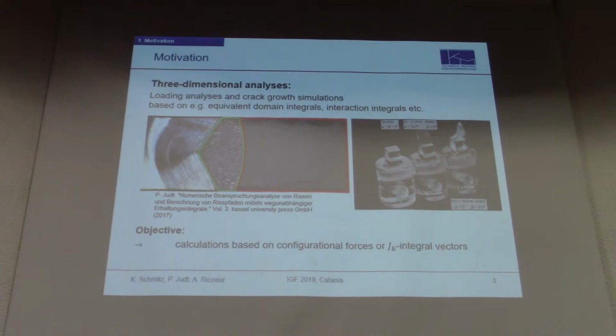three-dimensional crack growth behavior. For example, when we want to observe curvature of the crack front due to mode 1 loading, or crack deflection due to mixed mode 1-2 loading, or also the twisting of the crack front due to mixed mode 1-3 loading. Normally those calculations are based on, for example, equivalent domain integral formulations or interaction integrals. But the objective of this work is now to do these calculations based on configurational forces, respectively J integral vectors.